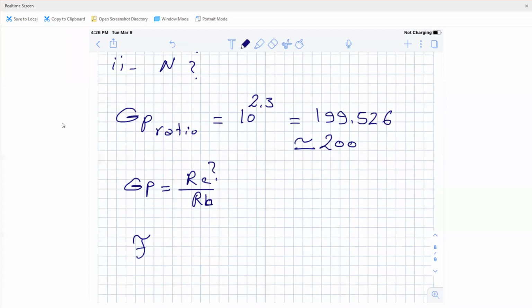The sampling frequency is 2 multiplied by 3.4, I mean 2 Fmax. Look, the low pass filter has a cutoff frequency equal to 3.4 kilohertz. It means that the maximum frequency here will be 3.4 kilo. So Fs will be 2 multiplied by 3.4 kilo, and it is 6.8 kilo samples per second.